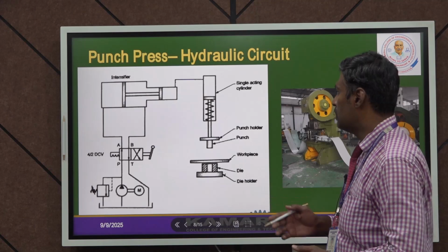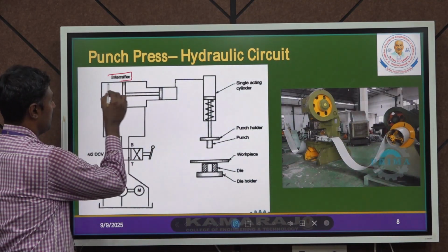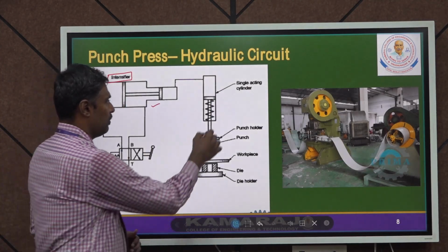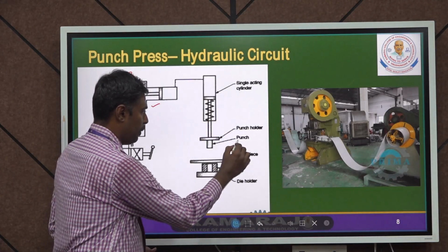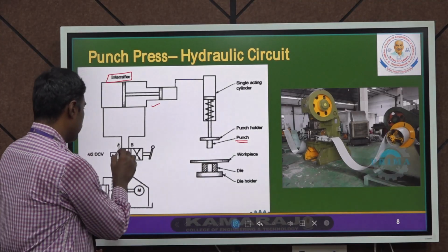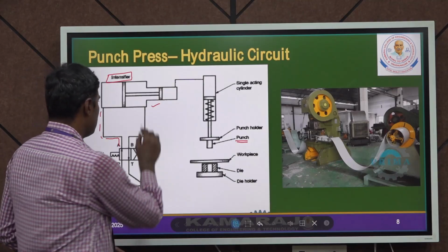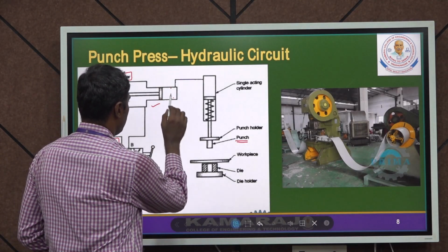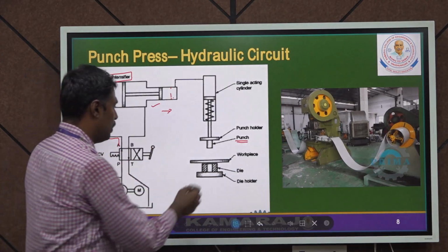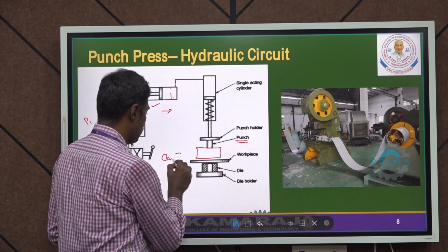And this is a punch press application, and here this is a pressure intensifier. Here a pressure intensifier is used along with single-acting cylinders. Here a punch is applied. The working of this punch press application is, once the cylinder is applied to port A with pressure 1, the cylinder gradually extends up to this end. It actuates in a slower manner with some ascent. After some time it is used just for clamping.